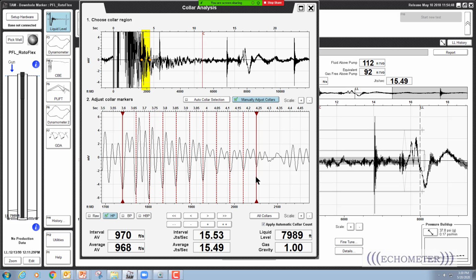So, maybe your preference in a well that has debris in the well is to do an explosion shot, even though the compact gas gun could do an implosion shot, because you don't really want to have to do maintenance on your gas gun. You could clean the wellhead and do an implosion shot. If you have the higher pressure gas guns, the 5,000 and 15,000 psi, they would work just fine with 1,000 pounds differential pressure. But maybe you would put less differential pressure in the gun because the fluid level is close to the surface. So that would be my answer.